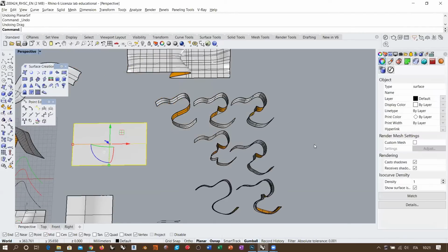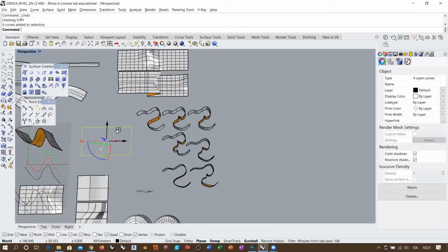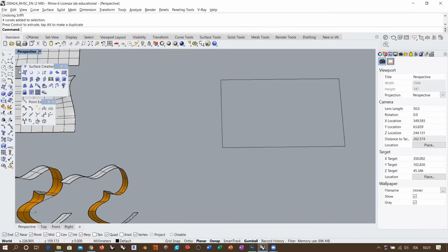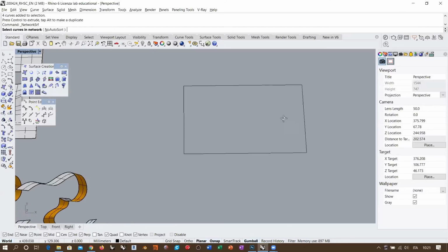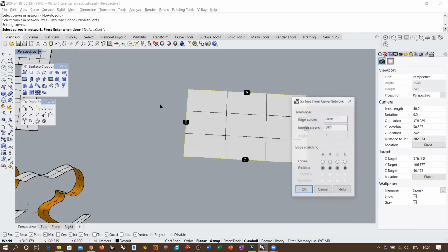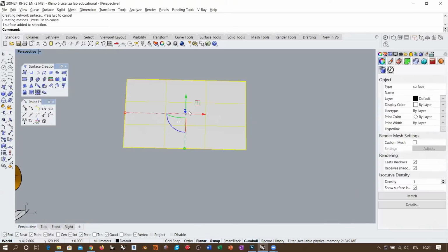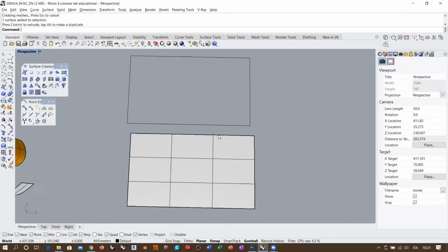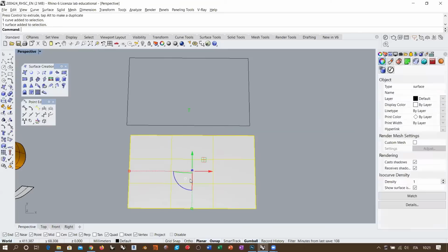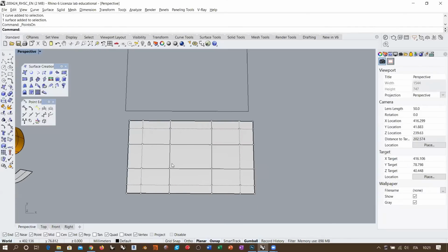So now, you see that it's evident that there is a difference between all these commands, right? But you also see that all the first commands that we have used produce more or less the same result, okay? Besides the orientation of the surface, that depends on the orientation of the curve, but the geometry and the topology are identical. But if you use, for example, the surface from network of curves with these very simple lines configuration, you already get this thing here. And despite the fact that you are using 4 edges which are straight and linear, you get a surface which has this kind of topology.